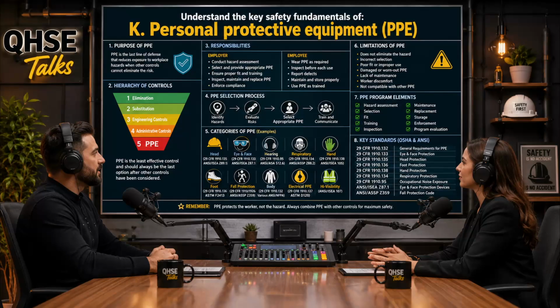Why? Because if a chemical vapor is toxic and corrosive enough to require a level A suit to protect human skin, that same vapor will rapidly eat through the rubber breathing hoses and expose valves of an air tank. So it protects the gear, too. By placing the worker and the SCBA inside the sealed bubble, you protect the life support equipment from chemical degradation. The suit seals completely around the worker, the tanks, and their boots and gloves. That level of isolation solves the chemical threat perfectly.